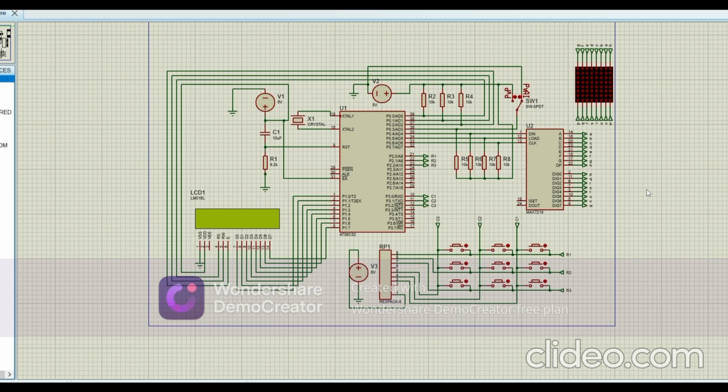Then step 3, the keypad scanning routine identifies which of the 9 cells was selected. If that cell is empty, it updates the board array in RAM. If the cell is already occupied, the move is rejected and the game waits again. Then step 4. The LCD is refreshed with the new board state and whose turn it is. And then the LED matrix is updated.